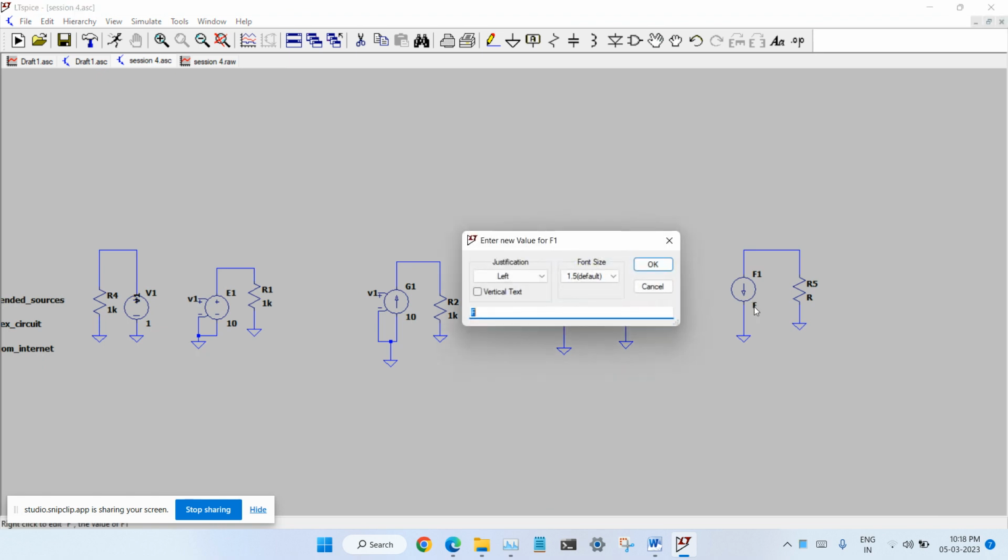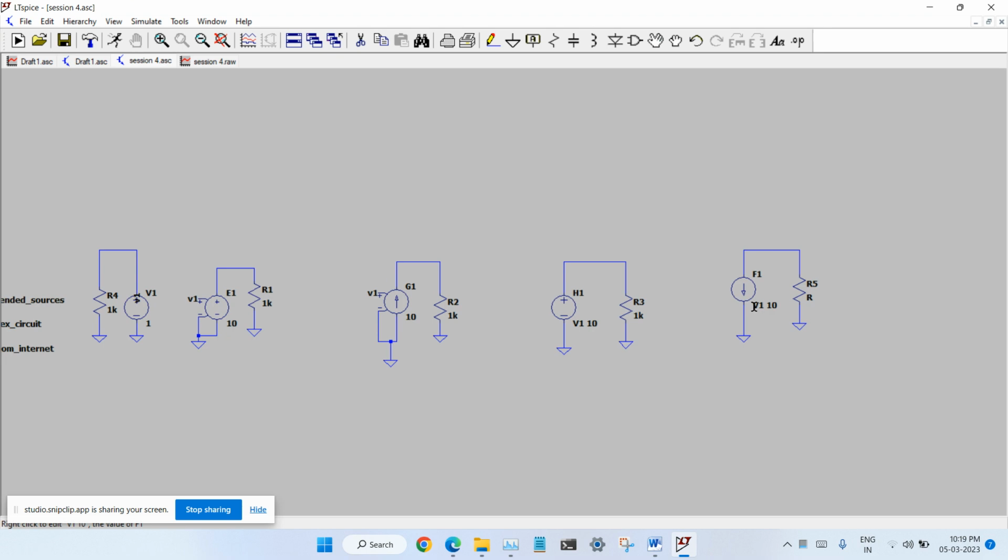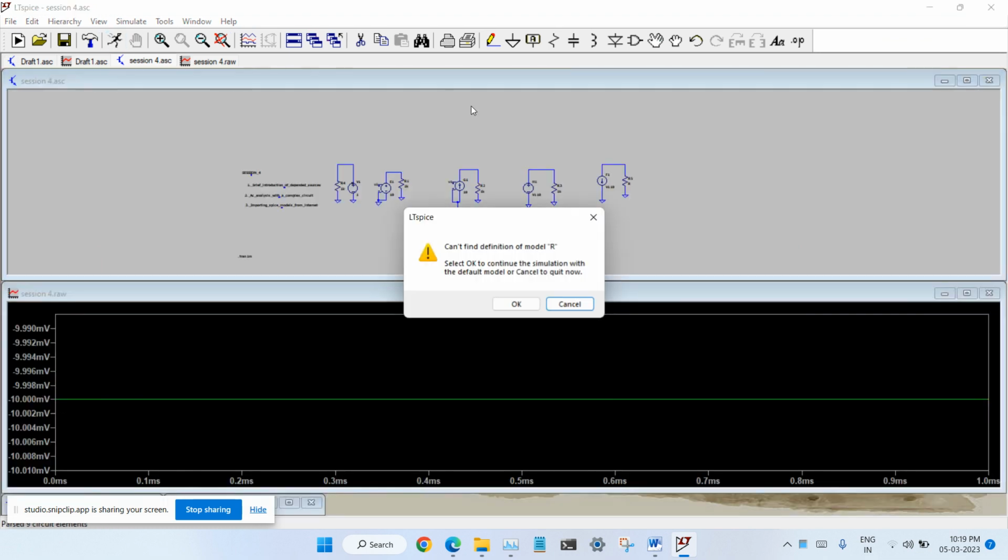a voltage source we should have. So we can take the voltage source capital V1 space 10 times, as usual 10 times is the multiplication factor. For this two we have to just give the multiplication factor, and here we should give the current through the voltage source we are taking and then the multiplication factor. Okay, so the current through here is 1 milliampere and we expect 10 milliampere through this. So let us see.